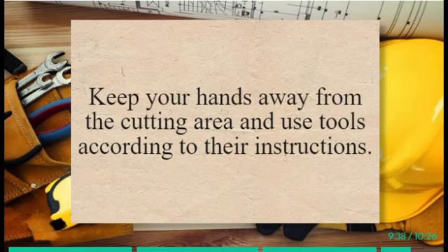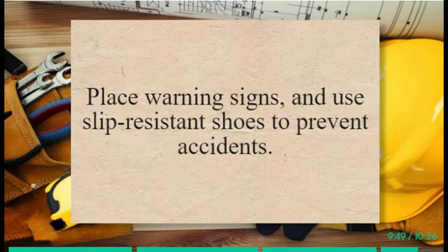Sharp tools handling. Handle tile cutters and wet saws carefully to prevent cuts. Keep your hands away from the cutting area, and use tools according to their instructions. Slip and fall prevention. During and after tile installation, be cautious of wet surfaces. Place warning signs, and use slip-resistant shoes to prevent accidents.